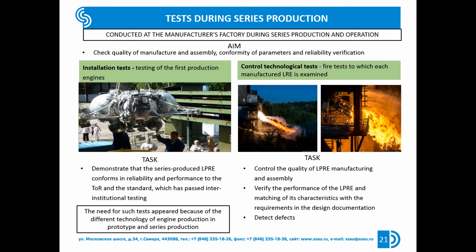Assembled LPREs are subjected to tests to verify the quality of their manufacture and assembly, their compliance with the main indicators with the declared parameters, as well as to check their reliability. After completion of preparations for serial production of a new LPRE or resumption of production of a previously manufactured LPRE, in-service tests are performed. The in-series tests are performed both on individual assemblies and on a complete LPRE.